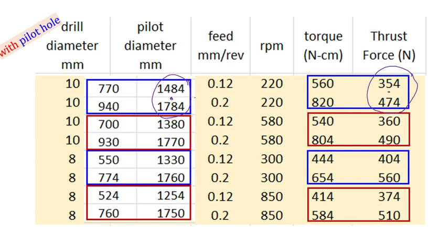It is almost 5 times less or 4.5 times less. So 80% of the thrust force is generated by the small chisel edge. However, if you compare, the torque is also going down. It is 770 and it is going down to 560, but it is not going down by 80% or anything like that. Everywhere it is the same story. So this is a question which should be asked in your report and you have to find out the answer for this.